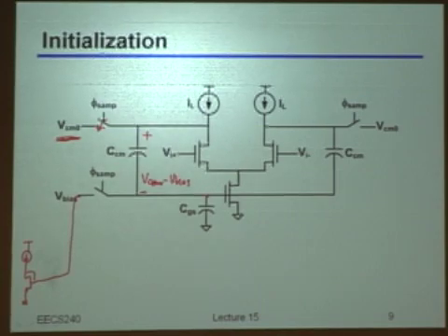So basically, I have my capacitor, I have my feedback. From time to time, at some phases, I just plug an external magic voltage there, and have my capacitor charged to that difference. And I have my output common mode just set to what I wanted it to be, right? So is that okay?